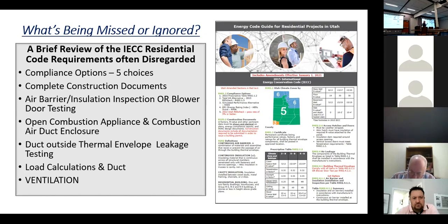And that's what we have with a loose house. And people say, well, at least then we have air quality. Well, not really, because it leaks around the perimeter and it never addresses the interior of the space. And then when the wind blows, it blows right through the house. And so ventilation by infiltration doesn't work.